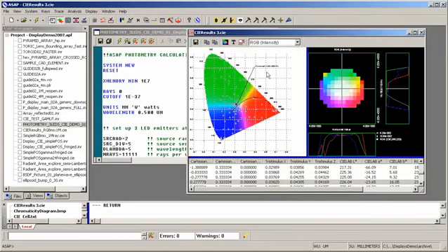So finally we return to the actual CIE analysis window, and we see something that looks rather white in the center, with a little bit of color noise, a little bit of green shading here, and a little bit of red, pinkish shading here, and blue here. We see the mixing in between red and blue into magenta. We see the mixing between blue and green into cyan. And we see the mixing between green and red into yellow. This is with a fairly limited number of rays.